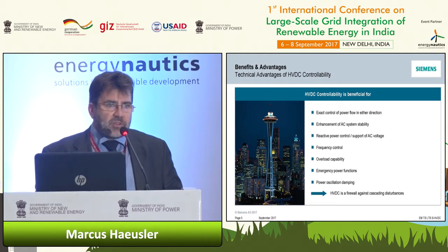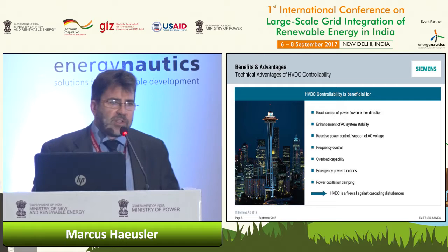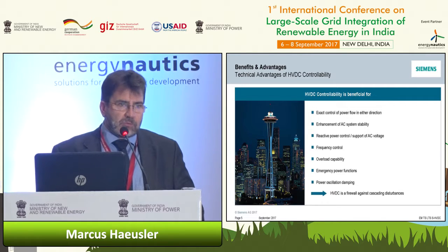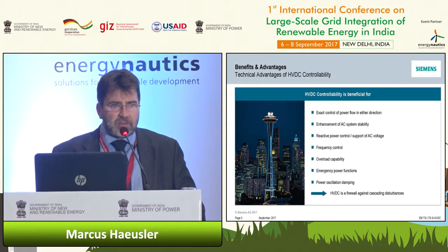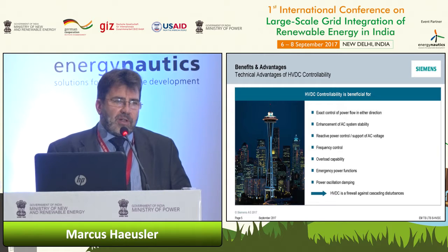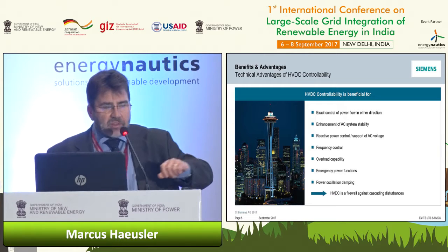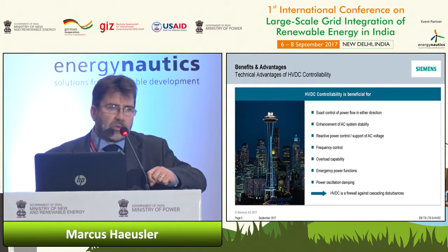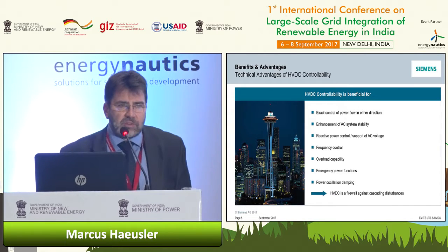HVDC, and especially the fast control of HVDC, is very beneficial in order to control the power flow, steady state, in both directions in a very accurate way. But it can be used also in order to dynamically enhance the stability of the power systems. And that means we can control not only the frequency by changing the power schedule of the DC link.